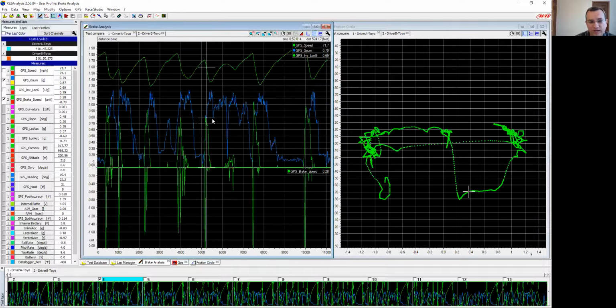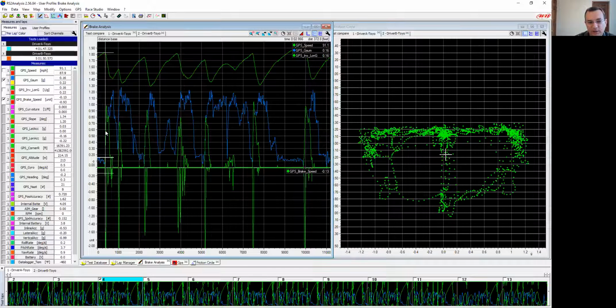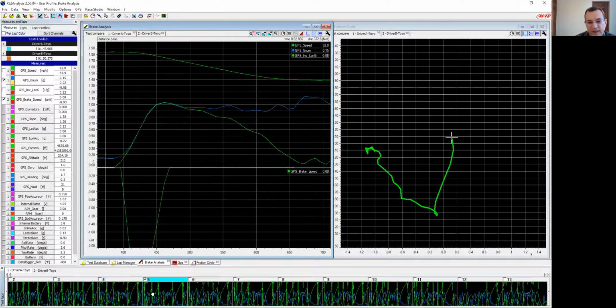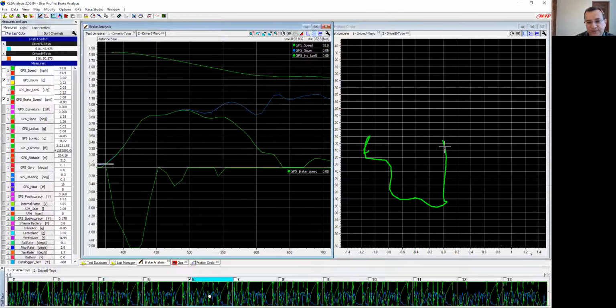Also, when we were scanning through those laps, we can pick a given corner like we were before with turn one. And as we scan through the laps, we can see there's a difference, right? Here's a good one, right? Where the braking G is held. But the one thing I don't like here, though, is my peak for braking isn't early. It's kind of in the middle, right?